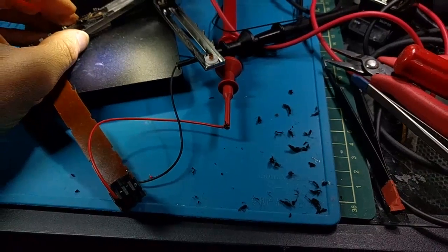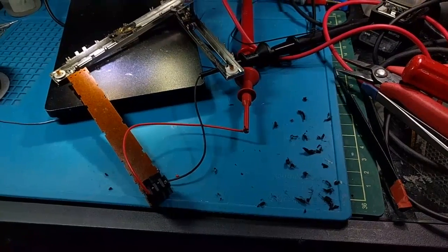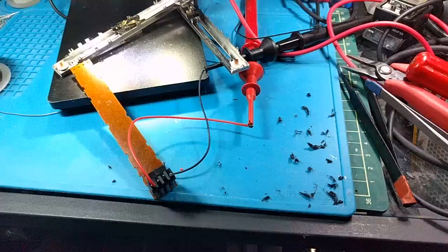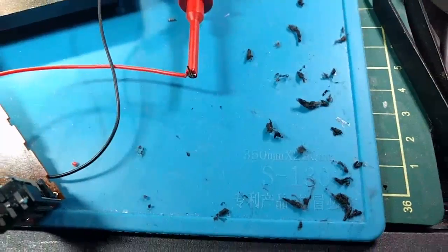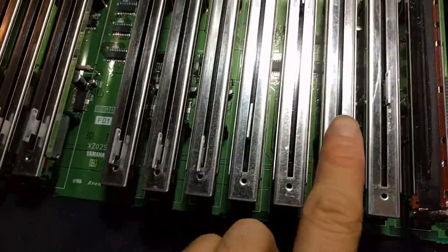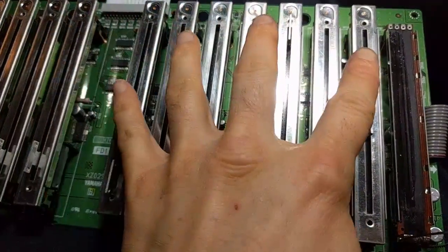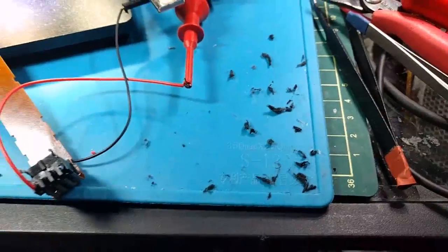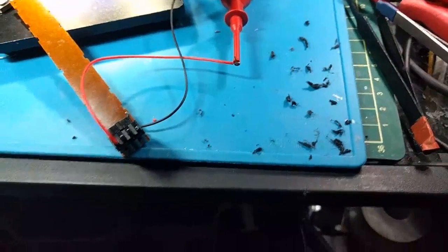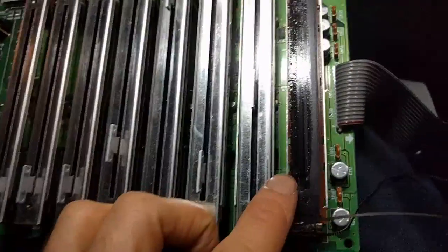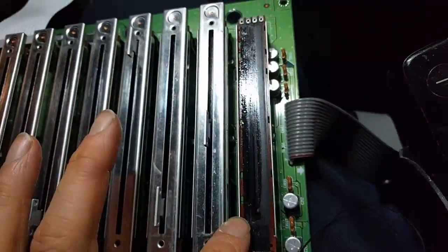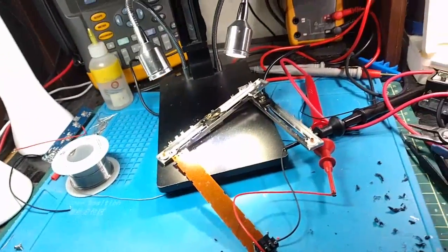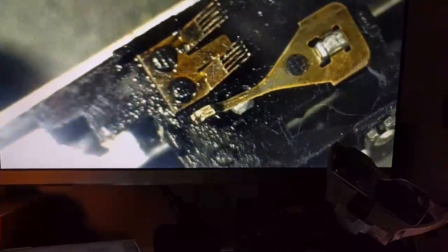Continuing the nasty fader repair for these Alps faders for large console mixers. Look at all this crap I found. This was after thoroughly vacuuming and using my air compressor really thoroughly on all the faders. This is all the crap that was still inside, and there's still a bunch more. One thing I want to make a note of is I used a bunch of DeoxIT in here hoping this would help, and I really think that's probably the opposite of what you should do. Really kind of regretting that now, because it will gunk up these little contact fingers.